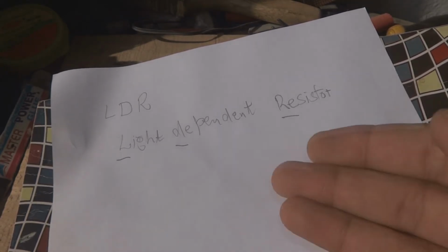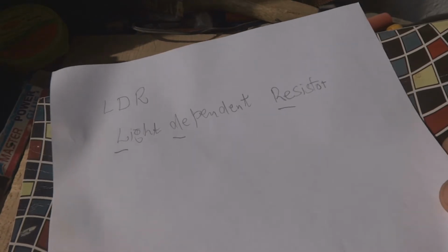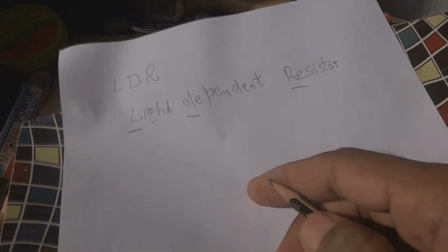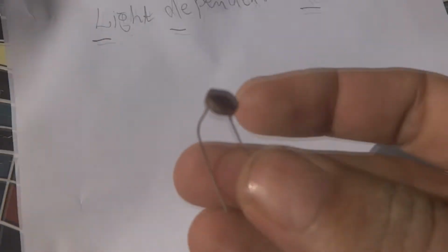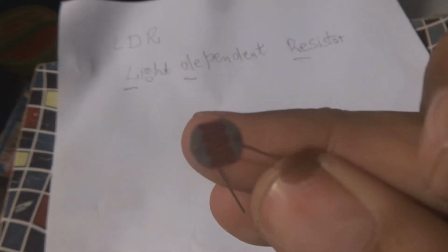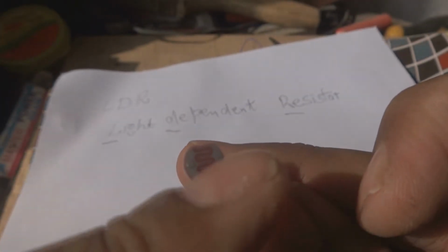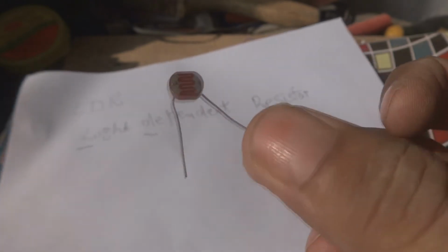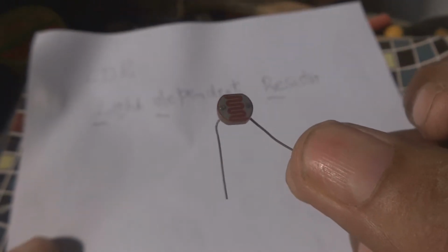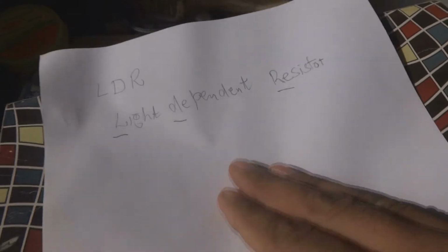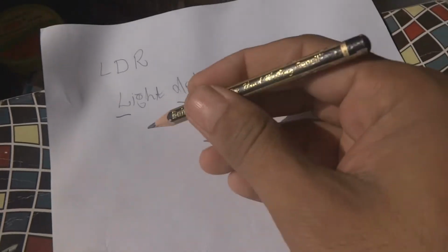Here I am going to demonstrate a little bit of theory also, so that you will understand the theory about this device. This is not only practical, it is theoretical as well as practical. Here is the LDR. This is the LDR, and it has a line inside, you can see, and it is made up of some semiconductor materials. There are two legs or two wires for this device. This is a 2-wire passive device like a resistance, but it depends upon the quantity of light. Very high resistance in dark and very low resistance in the light.